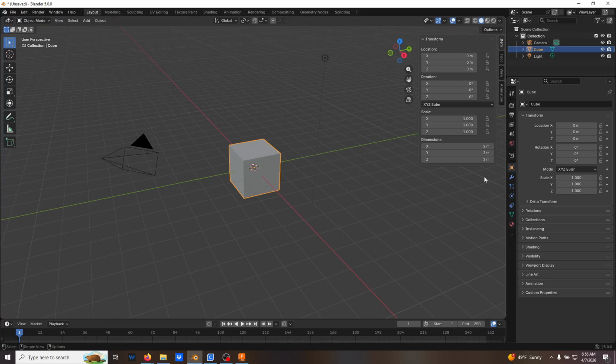This is meters, but you really don't need to worry about the units because STL files themselves are kind of unitless, and especially in Blender, the units are kind of like a convenience. But if you're doing rendering and lighting and all that stuff, that can come into play. But for right now, these are actually going to represent millimeters.